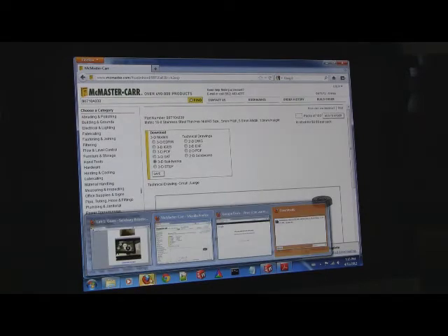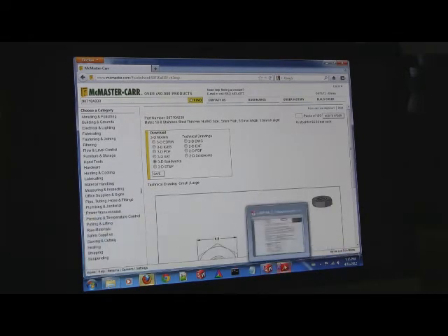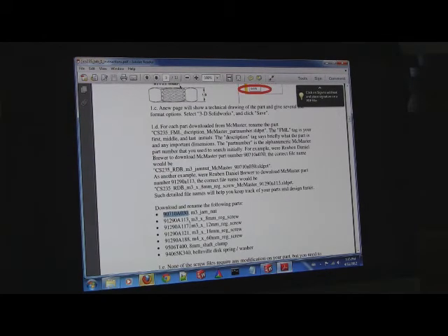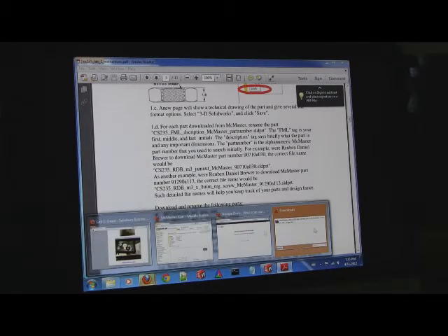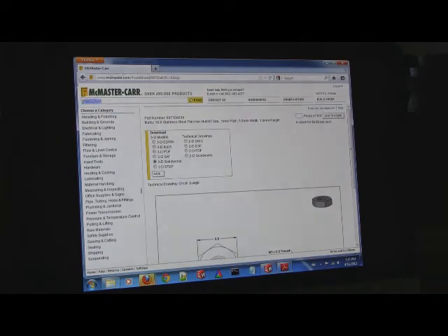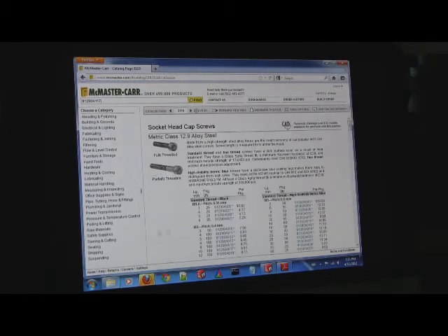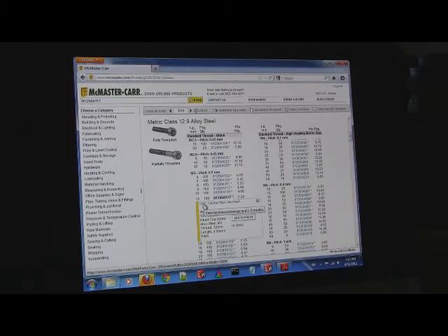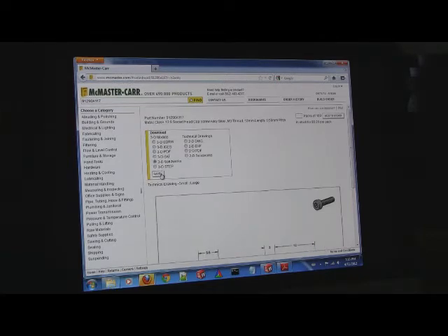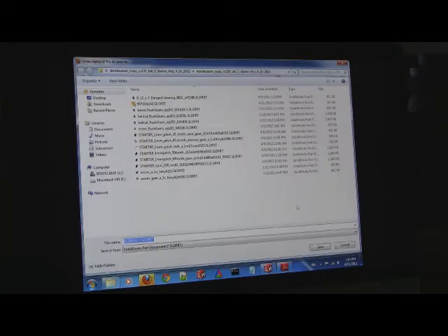Okay, and I'm going to do it again for a 12mm screw. So the 12mm screw has a part number 91290A117. Again, press the CAD button in the lower left of the pop-up. 3D SolidWorks, save, and then save it to your folder, and you probably want to name it something like M3 by 12mm by part number. It's fine for now, just so you know what it is.